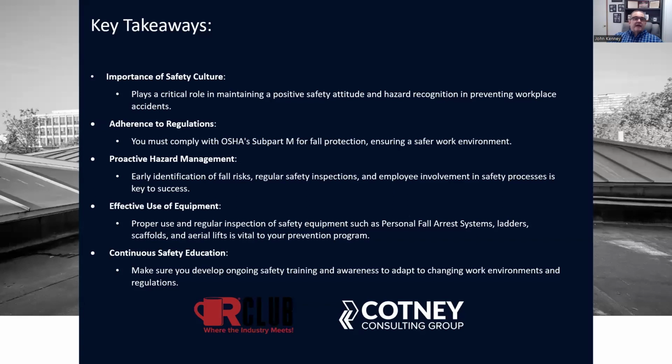So what were the key takeaways today? So again, first of all, you got to start out with a safety culture. This plays a critical role in maintaining a positive safety attitude, recognition of hazards, and preventing all workplace accidents. Start with the culture, absolutely important. Then you must adhere to the OSHA subpart M's that we talked about. Go there, read them, understand them. Make sure that your safety program takes all those into consideration when you develop it and train on it.